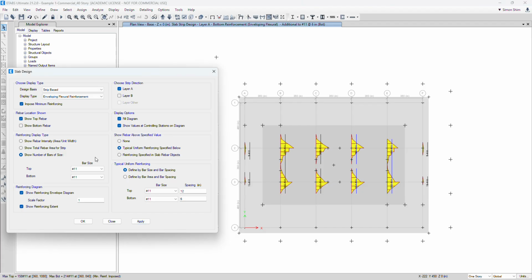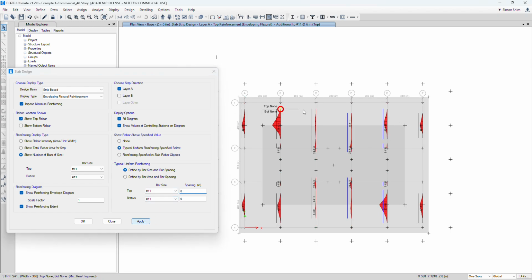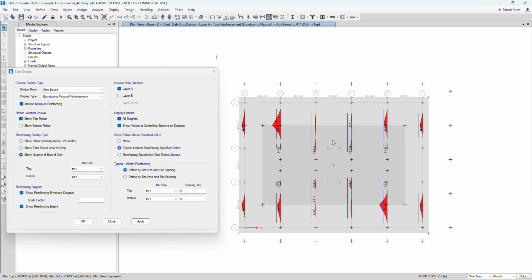And I think you could do the top bar, right? This is the top bar if you're using 6 inches, right? This is additional bar. So this is mostly output. Graphically, you can figure out how much reinforcement we need. So again, after analysis is complete, save ETABS and analyze the overall area of bars. What size of bar, what spacing of bar and where is something you can graphically walk through and choose. We are the engineer, we choose it. So we need some iteration to choose the number of bars and location of bars.